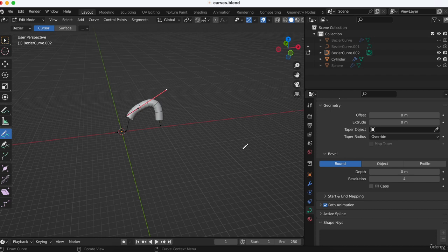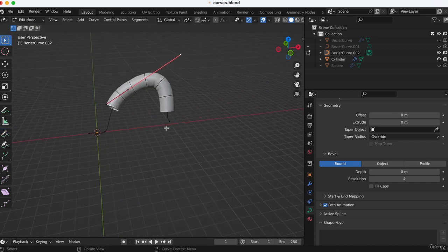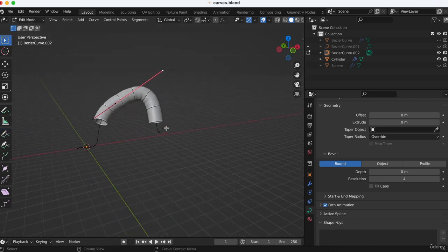We worked with subdivision surface to make smooth shapes, which are really easy and also really fun. We did some modeling with curves, with the screw modifiers, with the object on curve, and now you have everything to start modeling objects you want, or even characters.